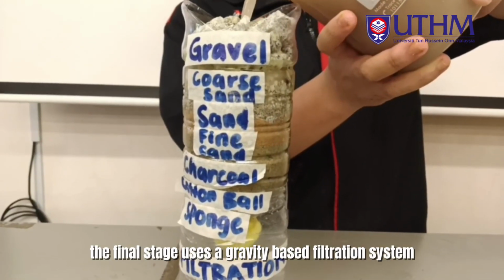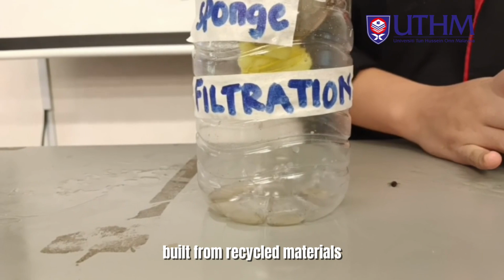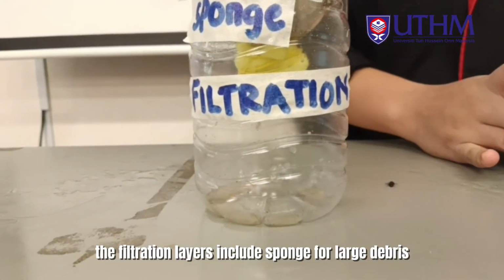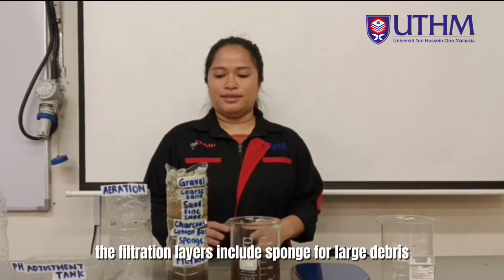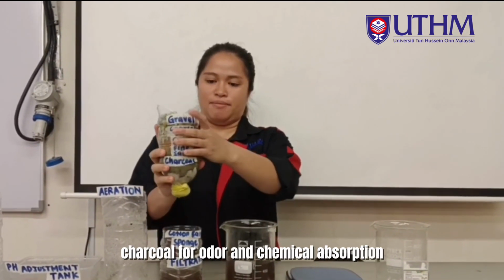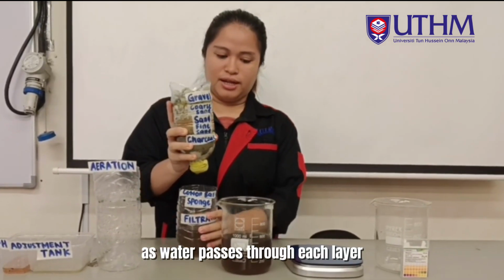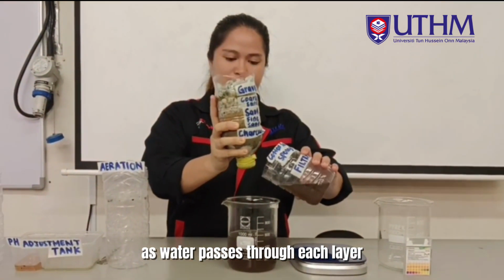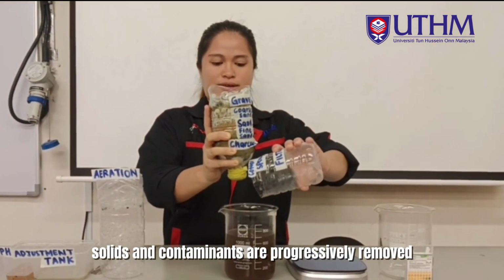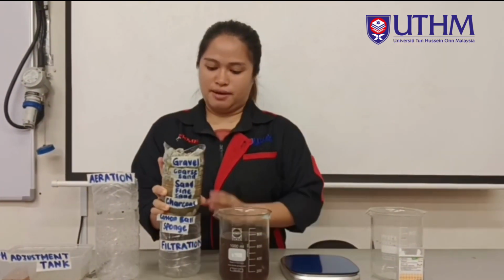The final stage uses a gravity-based filtration system built from recycled materials. The filtration layers include sponge for large debris, coffee filter for intermediate solids, charcoal for odor and chemical absorption, and fine sand for final polishing. As water passes through each layer, solids and contaminants are progressively removed, resulting in visibly clearer effluent.